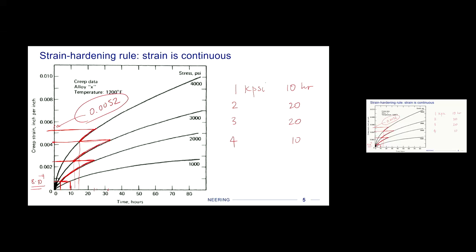And in this case, instead of really taking into consideration the time history, we're now considering the strain history to be more important as we add up the strains, right? So if we have alloy X here, we don't know what it is, but we look up general information about it and we find out that creep strain is usually controlled by the strain history, we're going to use this method. If we find it's usually controlled by the time history, we use the prior one. Okay. So those are the first two.